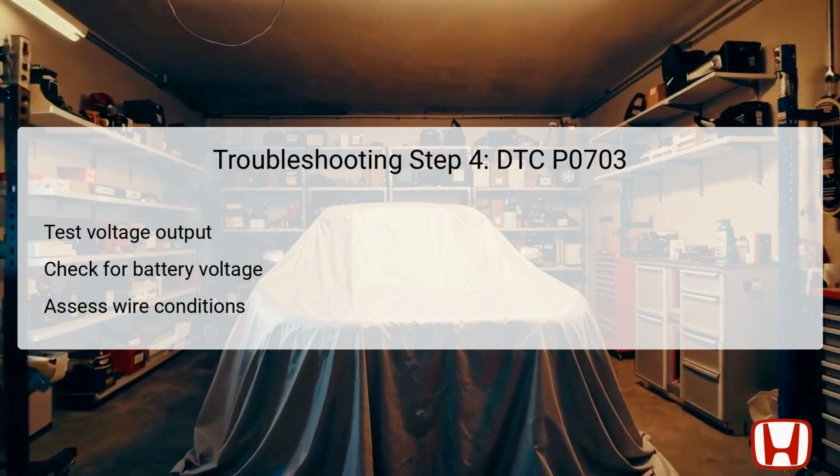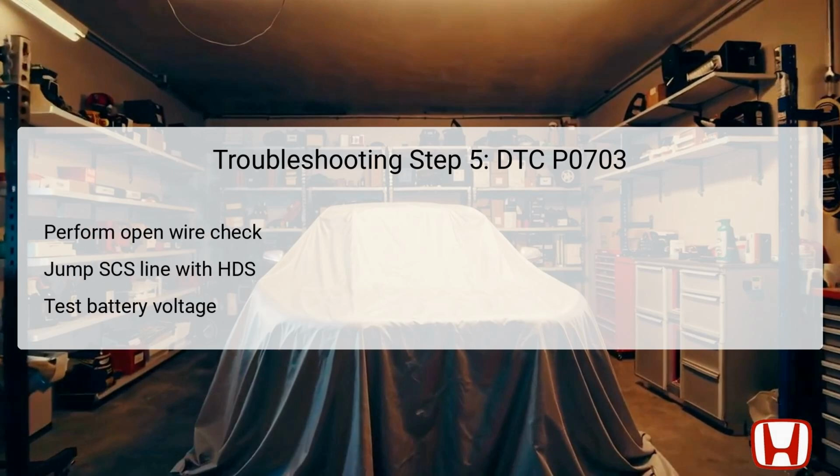These points include the brake pedal position switch connector number 4 and the vehicle's body ground. Confirming the presence of battery voltage in this scenario indicates that the IG1 ACG wire is functioning correctly, allowing you to progress to Step 5. Conversely, if no voltage is detected, prepare to initiate repairs, as there might be an issue that affects the circuit integrity.